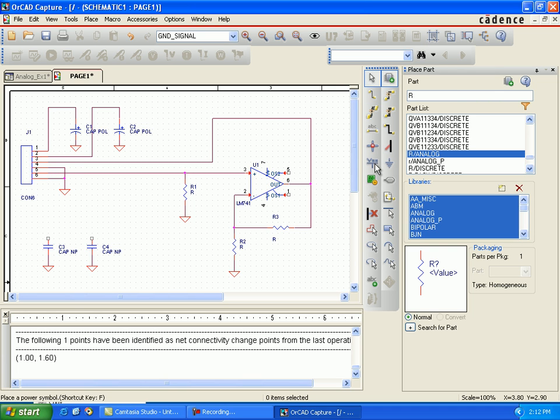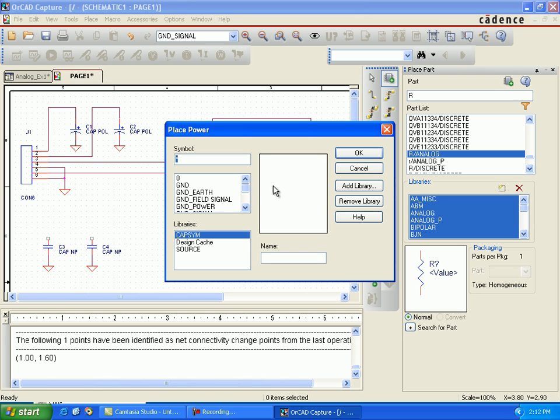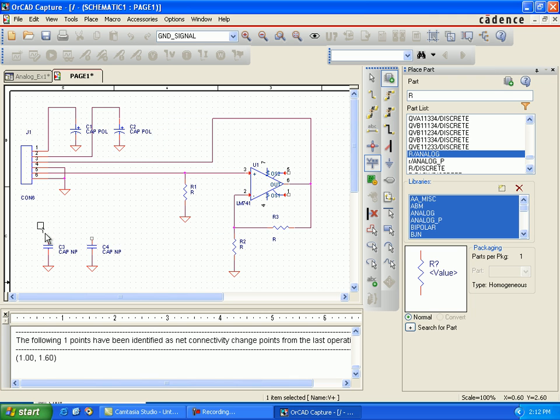So between 5 and 6 we are giving input, and between 4 and 5 we are taking the output. So pin number 5 is the input and pin number 4 is the output. Take care of this confusion. In the 6-pin connector we give the inputs and outputs, and inside the PCB there is a power supply for the op-amp.